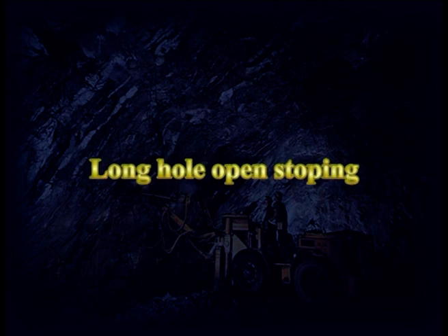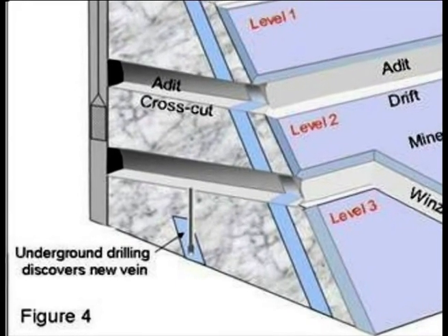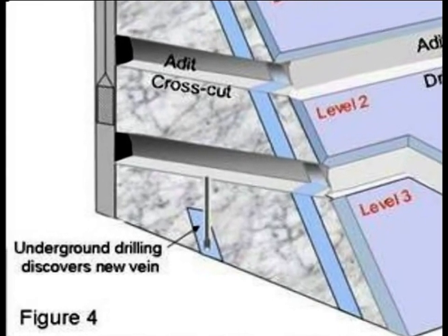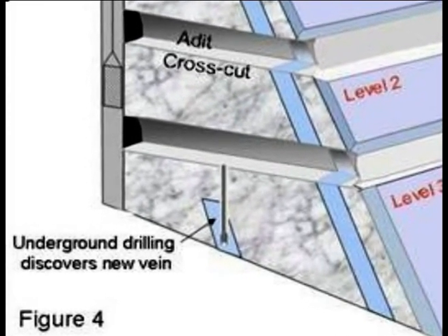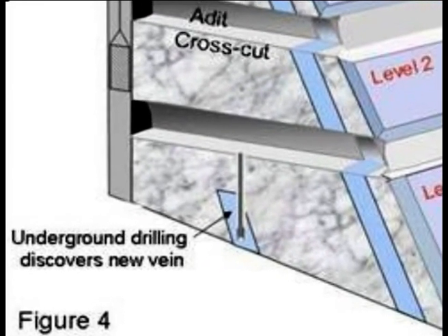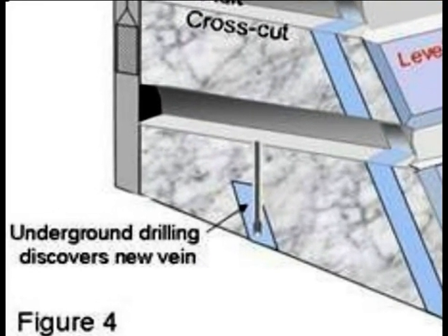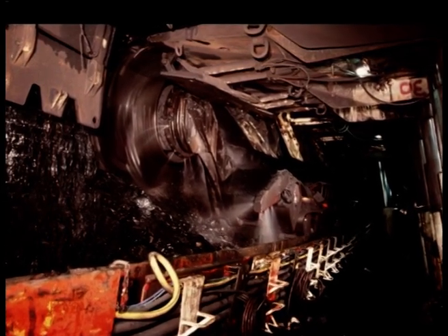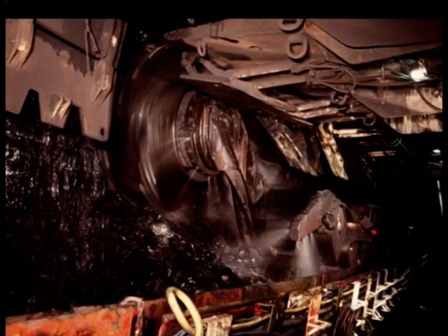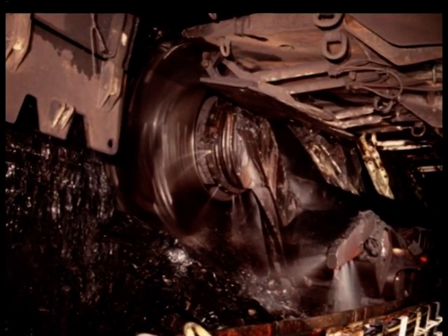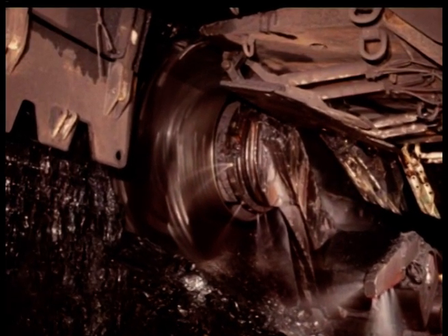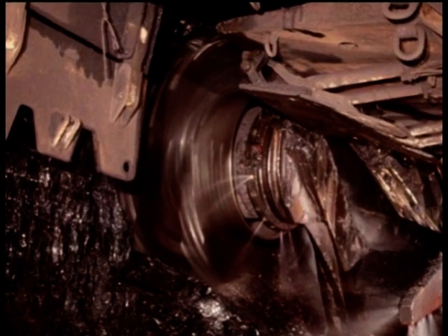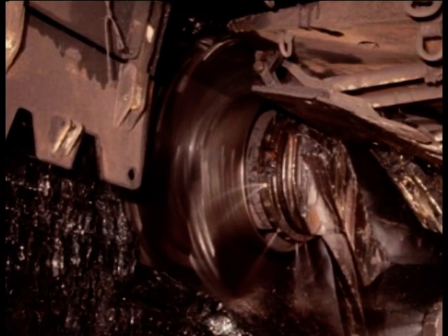Third, long hole open stoping. It is a less labor intensive variety of sublevel stoping in which larger blocks of relatively uniform ore can be taken by fan drilling and massive blasting from locations in the sublevels. The drill hole fan pattern must be carefully designed and controlled so that unbroken boulders of ore will not be left and so that wall rock will not be blasted loose and allowed to dilute the ore. The broken ore is extracted from draw points on a lower level.